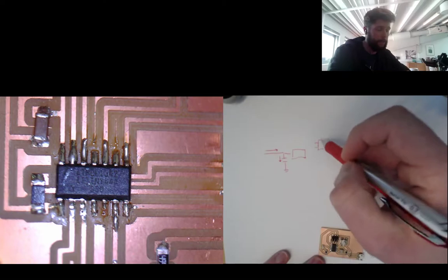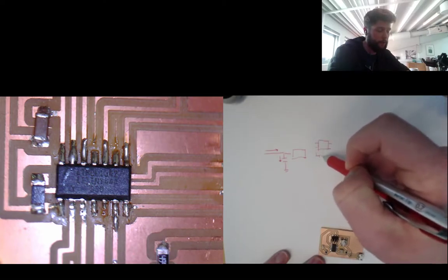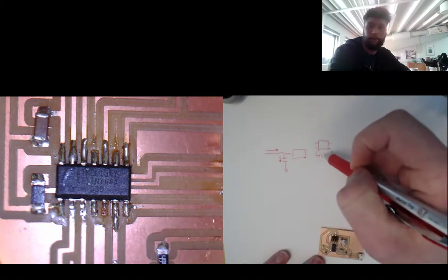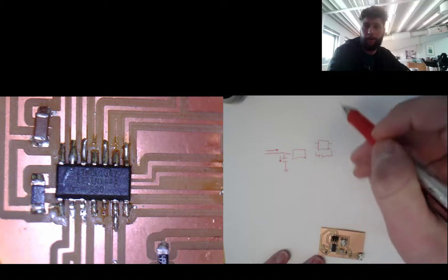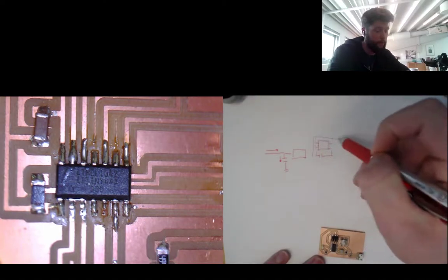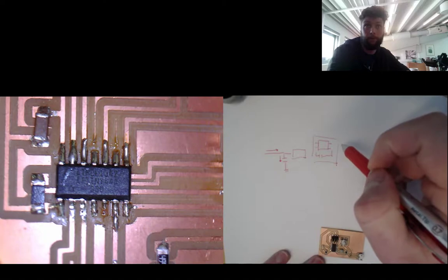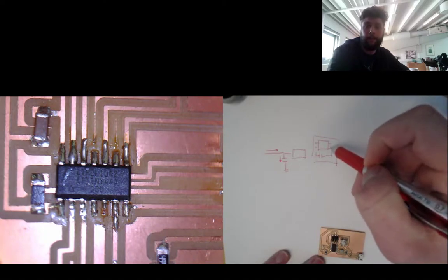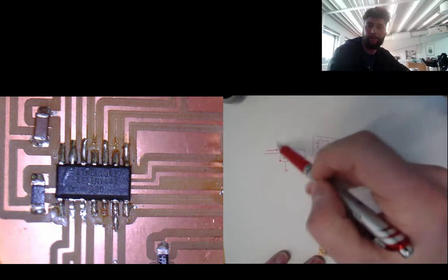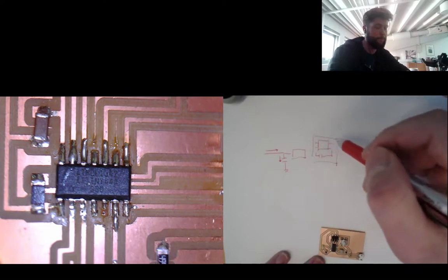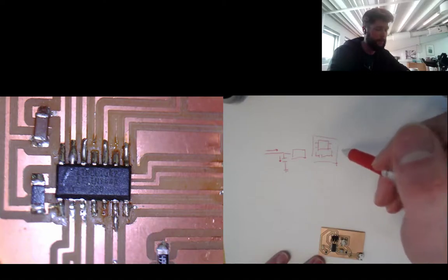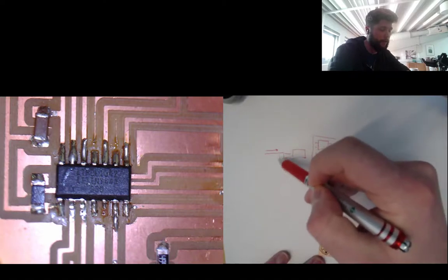Milliamperes. So that's why we have capacitors in between the ground and the power and the voltage in. That's to filter out all the hectic power input. It's both to protect the component that we're placing, and it's also to protect the power supply, the component that gives us power to the circuitry. Any questions related to that specifically? Maybe not. So either way, that's why we have the capacitor.